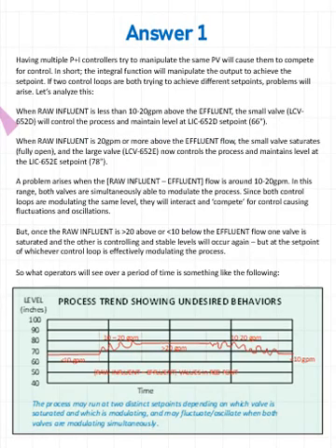So having multiple controllers try to manipulate the same process variable, level in this case, is going to cause them to compete for control. Let's analyze this a little bit. This is a lot like having two children assigned to put the same toy in two different bedrooms. There's going to be a tug of war. It can't be in two places at once. It can't be at two set points at once.